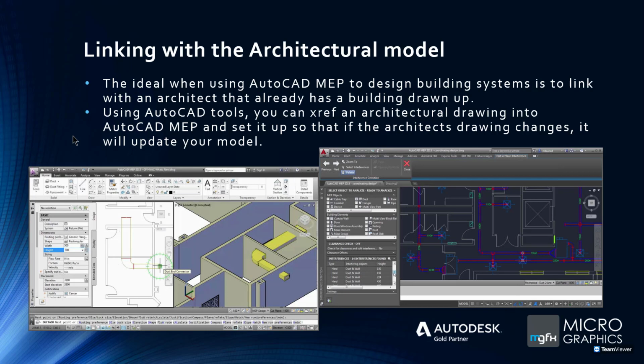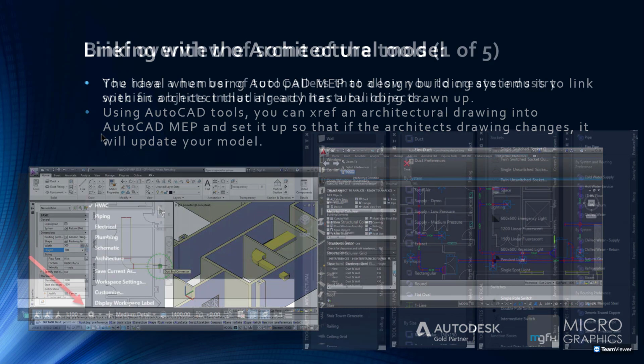Even if you export it from Revit to a DWG, that DWG you would basically link in or xref in, and if that changes from the architect, it'll update your components or your 3D walls, doors, and windows.